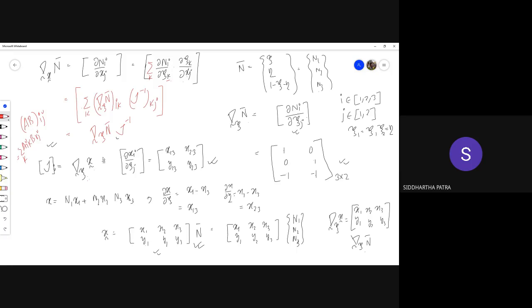But I need you to note one point with the type of element that we are using. You see, none of the terms are functions of ξ or η. In the Jacobian, none of the terms are functions of ξ and η. You see these x1, x2, x3, and everything else, which populate the Jacobian matrix, are actually combinations of the nodal coordinates, and the coordinates of the nodes are not functions of ξ and η.